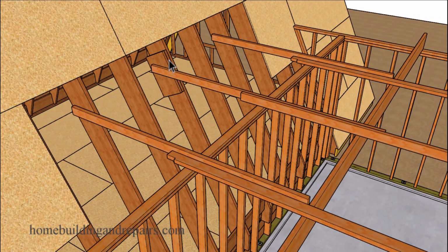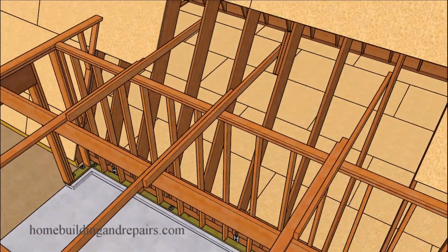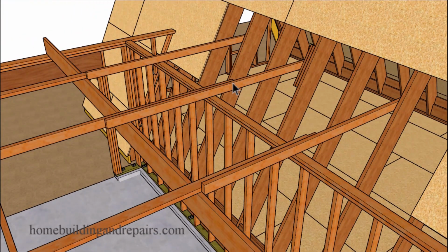And here I had to attach a couple of blocks so that I could connect the brace that will be thoroughly nailed to the other support brace that will be sitting on top of the rafter ties. And you should attach all of this stuff together. End nail the flat board to the rafter tie, toe nail this board to the rafter tie, and again, you can just end nail, drive some nails down through the 2x4 into the rafter tie, and then drive some nails through this 2x4 into this 2x4, and then some nails to connect the rafter here to the brace. And hopefully you don't need more information on that.